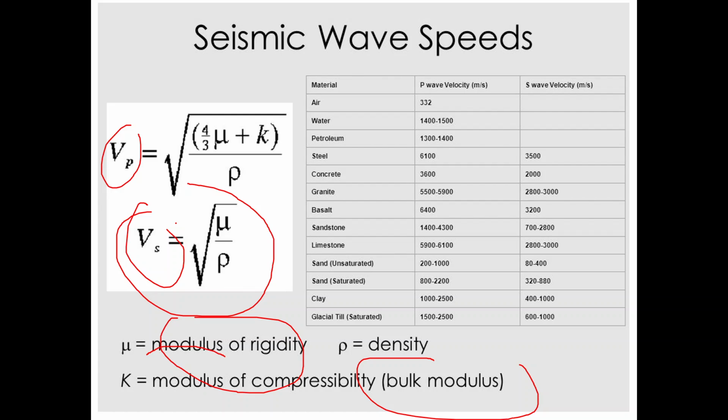For water, for example here, the best thing about the S wave is that it has zero velocity in water or petroleum or in air. So meaning here, if you have saturated material, like in our part Raja, the technique of P waves is sometimes quite difficult for differentiating the soil profile.